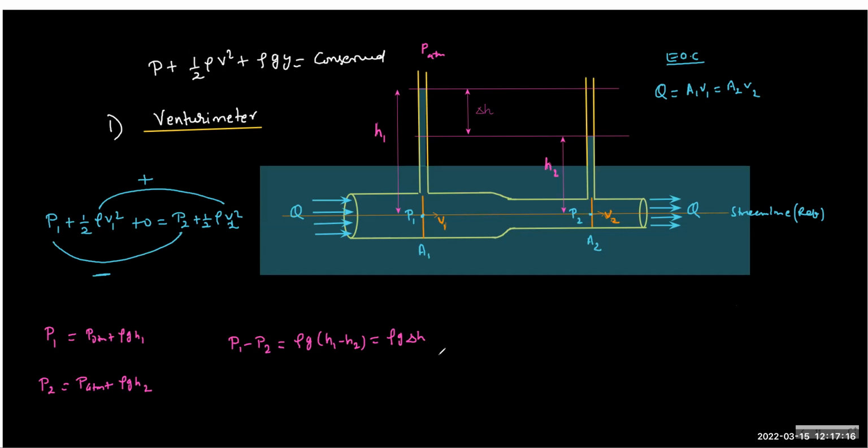So the static pressure is always calculated in terms of finding the height of the liquid rise and fall in the tube attached to the flow tube. So the flow tube is different. The purpose of attaching these vertical tubes is to understand how much pressure is actually present there, because otherwise you cannot see the pressure. There is no way to know the pressure without attaching these tubes.